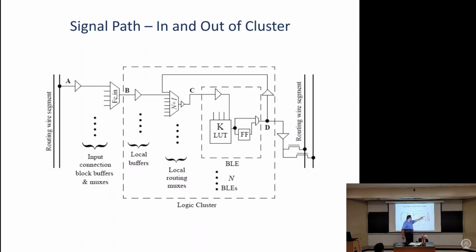So basically, they built a big buffer here and then big pass transistors, because this is capacitive. So these are not small pass transistors. They're large, because you're right, this has a lot of capacitance. These have to be sizable. So good question. There actually are improvements in routing architecture since this date. So you probably wouldn't build it that way now. There are better ways that are known to build it, and there's a paper called direct drive routing that lays out that trade-off.